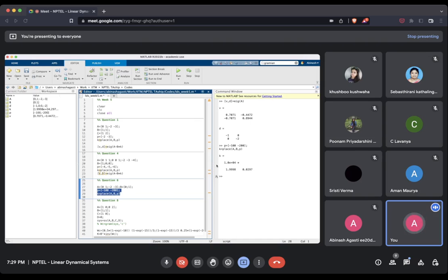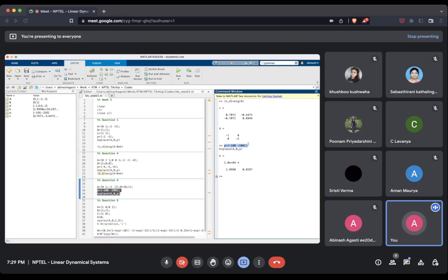See, if I try to push the desired eigenvalues too far away on the left hand side, the demand on the control becomes so high. So u is what? Minus Kx, right? So u has to amplify the state this largely, like 10 to the power 4. That's a huge magnitude, right?